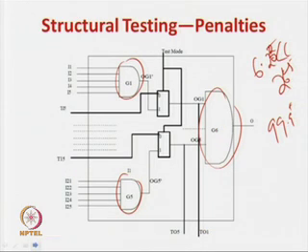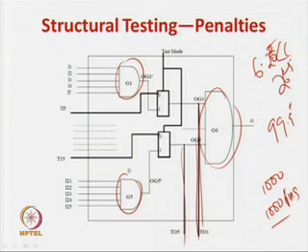So for these cases, for the outputs of this gate and this gate, we have brought them out as separate pins. So this is one kind of a penalty. If there are around 1000 such nets to be observed, then you require 1000 extra pins, which is infeasible. So we will slowly see how we can do away with this. But another more important problem that has arisen now is that this AND gate was directly connected by this one, and similarly for this. Now what has happened is,